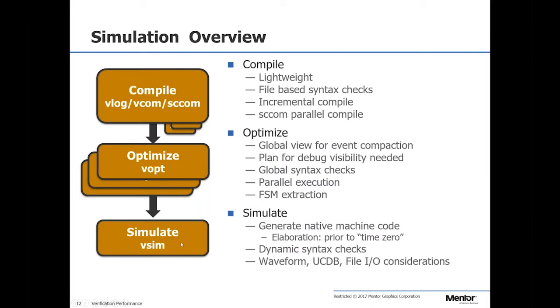If you're a ModelSim user, you probably use vlog or vcom to compile your code, and then you do vsim to simulate your code. What Questa does is it has this third step that happens between those, called vopt. What happens during vopt is that it does a lot of global optimizations. It looks for ways to combine always blocks or processes within your design.